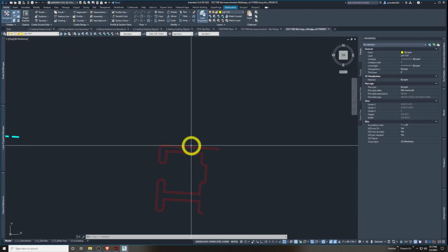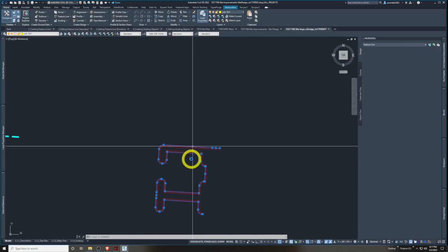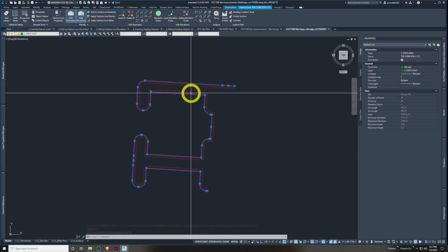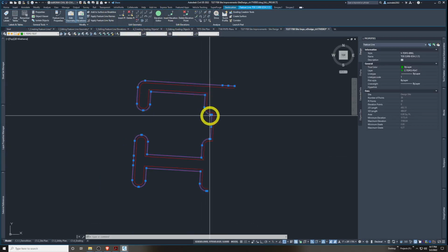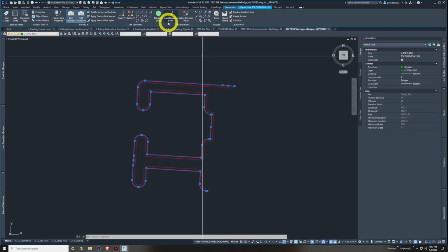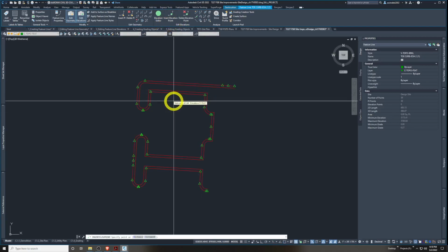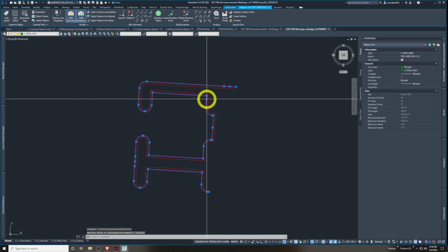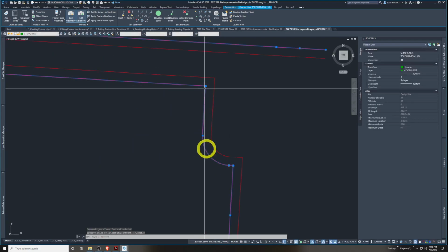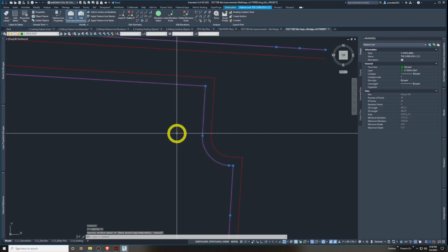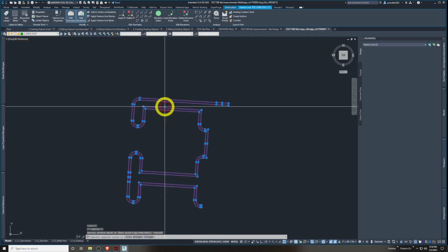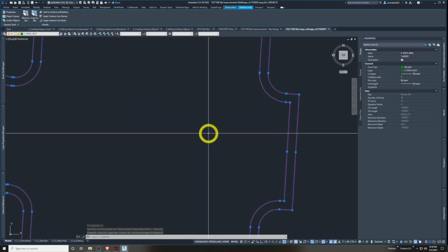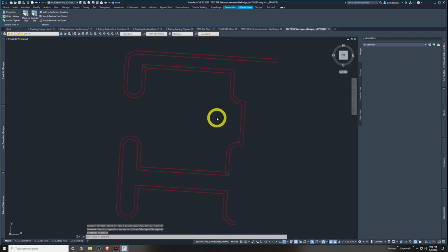And also with this feature line here, you saw its elevations and its Civil 3D stuff inside of it. This is all just PIs. So I don't have any elevation points here, which I could add here. They're all the triangular grip, but really the blue grip, the square grip. So that means they can move in any direction. So this one's a pretty pure geometry that I used to design a curb of a little interior parking lot, but this just gives you a good idea of the start of feature lines.